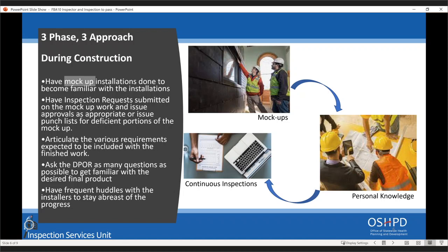So now you've done all your upfront work. You've got your schedules. You've been notified. You're getting ready for the actual inspections themselves. Well, what you got to do, you got to know what's being installed out in the field. We used to call it WANs, or WAN, for a wide area notice as to where electrical was being installed, where drywall was going in place, ceilings, etc., so that you, the inspector, know exactly what areas of the project are being worked at any one time.